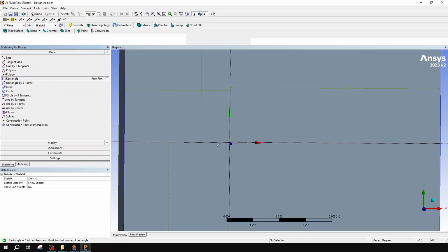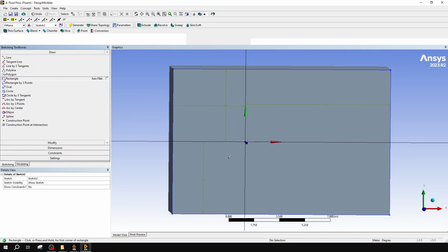So again, just moving over to rectangle, you might have seen that C appear. Anytime it's going to make something coincident, which means on top of a pre-existing line, it'll have this C, just so you know that it's auto-locking to that line. But we don't want that for now, so I'm going to make this front just free-floating, but I do want it to span the entire geometry of our box, so I do want it coincident with our back edge.